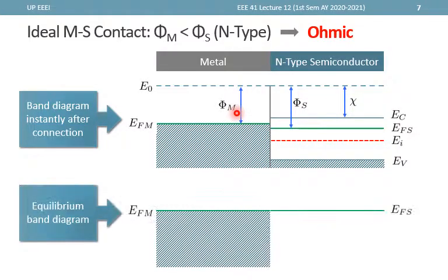So again, when we draw the equilibrium energy band diagram, we start with the flat Fermi level, and then take note of the energy levels at the interface, except for the Fermi level in the semiconductor, since this one actually moves to flatten the two curves at the interface.